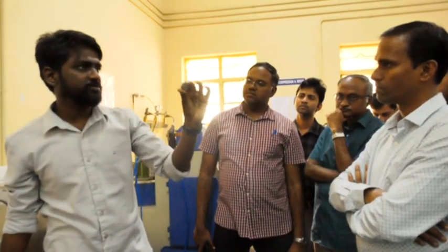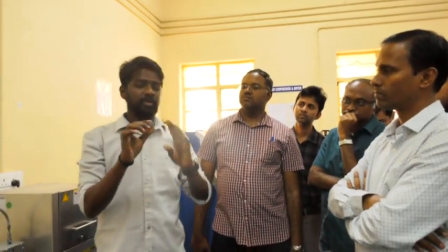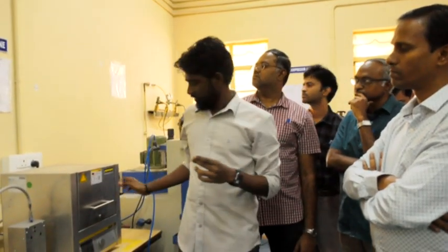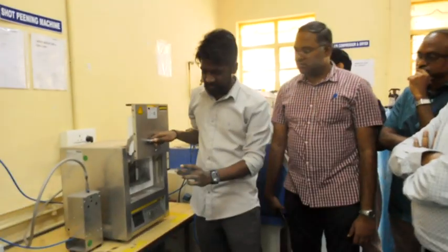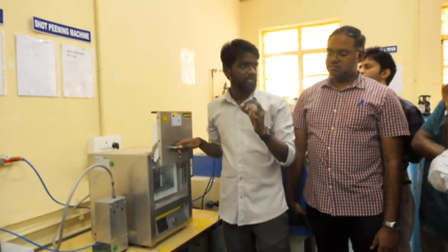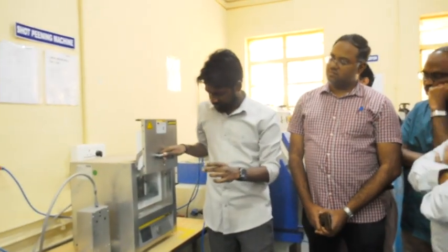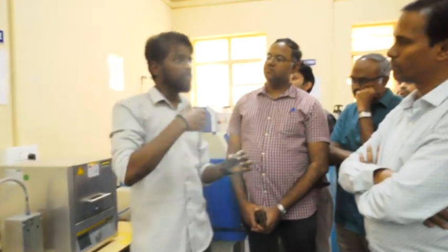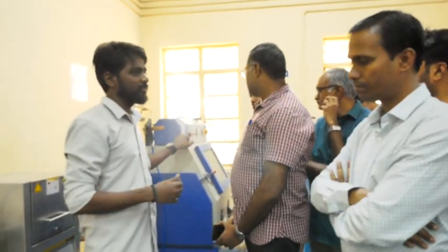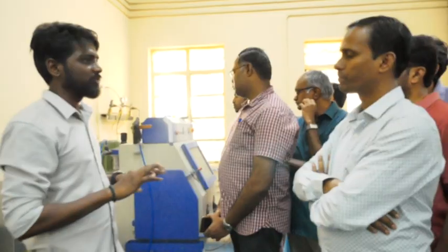Right? After cutting with the wire machine, we can get this part. Suppose, for example, we have to do some heat treatment process. Right now we are having a muffle furnace. So after keeping it inside the muffle furnace, you have to do heat treatment or aging kind of thing to increase the proper mechanical properties finally. And after that, you have to improve the surface roughness or surface treatment. You have to follow sandblasting, or you used to call it shot peening. Different names will be there, but the process is the same.